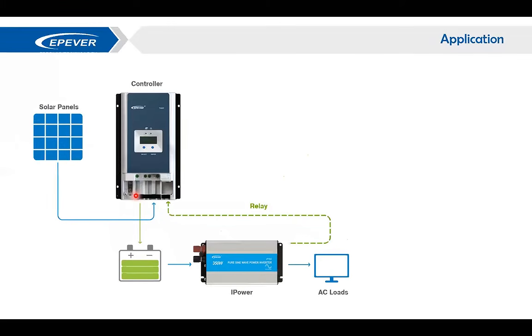As another example, it can work with Tracer 50 to 100 amperes to control the inverter. So this is the Tracer series, and they can work up to 100 ampere capacity, and they are parallelable, so you can connect them in parallel together up to 8 charge controllers, and this will help you increase the capacity of your off-grid system.